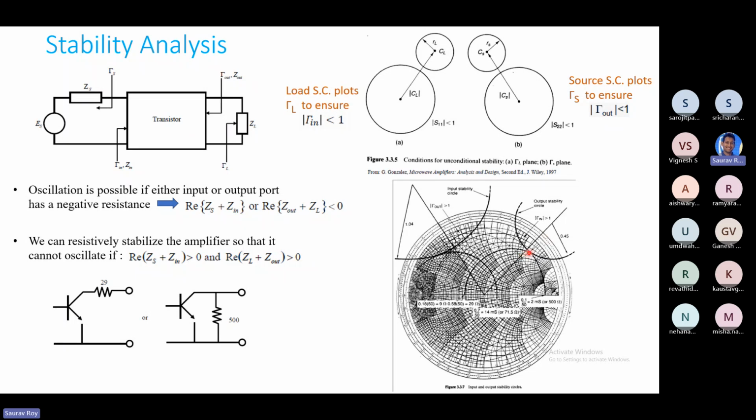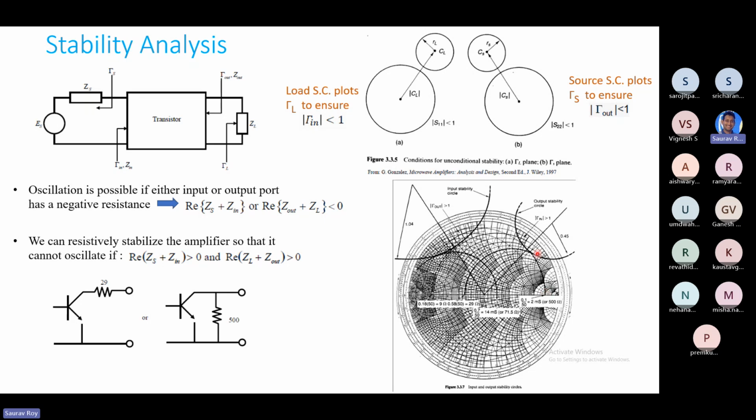So how do we do this? From here, in this admittance chart, we find out what the admittance value is. This corresponds to this circle, which is 0.1. And if you divide this 0.1 by 50, you get the admittance, or correspondingly, it gives you 500 ohm. Okay. So as you see, it is important to understand the Smith chart. Because this point overlaps with this admittance circle, that tells you the admittance point here is 0.1, or you divide 50 by 0.1, then it becomes 500 ohm.